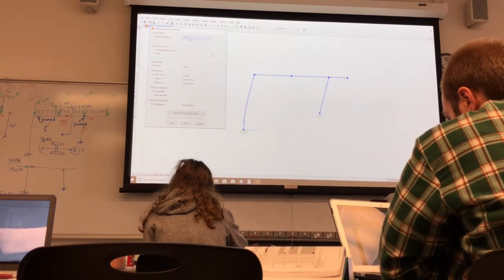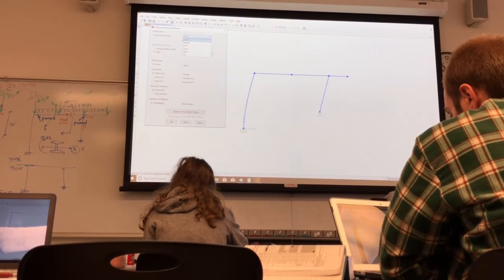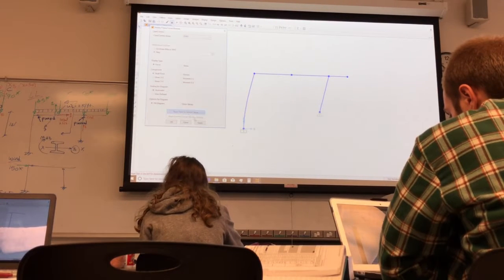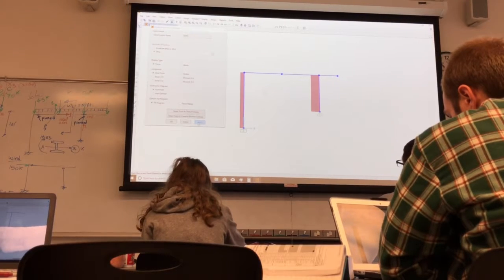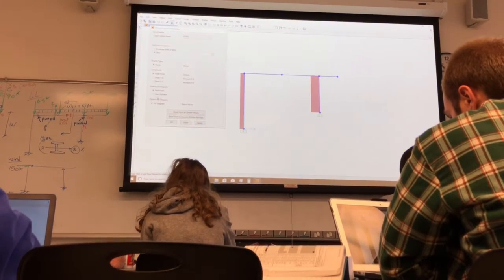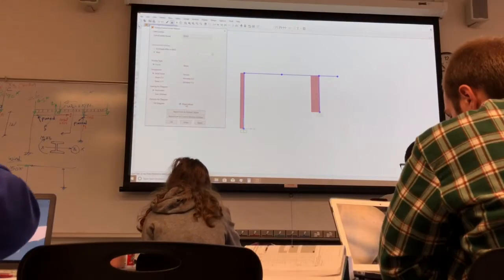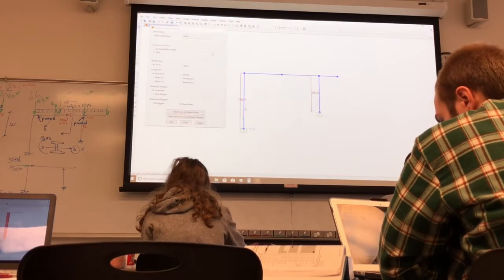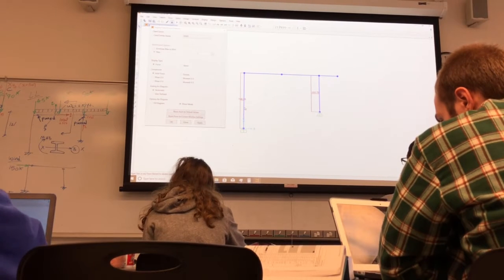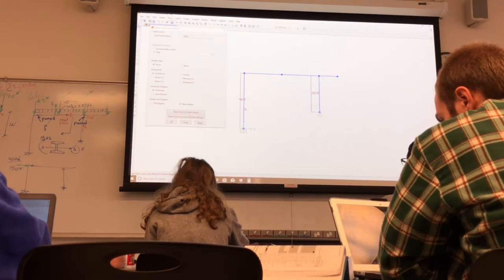Here it shows many options. You have dead load, you have the whole list of loads, and if you click apply dead load, we selected axial force. So that's the axial force. We can have it as show values instead of a fill diagram. So you see you got 146. If you do the analysis, you'll end up with the same answer.